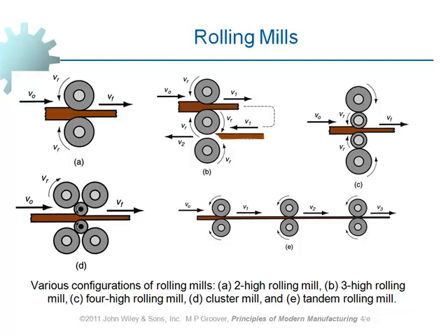And here we can see a number of methods which are used in order to roll the material in rolling mills. This method is called a two-high rolling mill because two rolls are being used in order to roll the material. This one is called three-high rolling, when material is being rolled once and it returns to the other pair of rolls and is subjected to rolling again. So it's been rolled twice instead of once. Of course, we can achieve a greater change of geometry and shape.